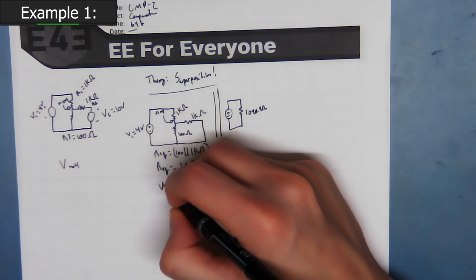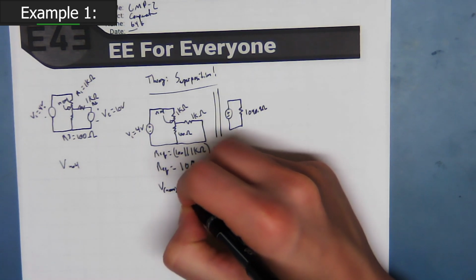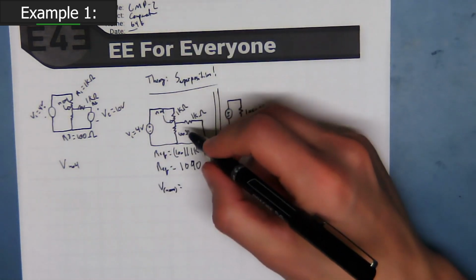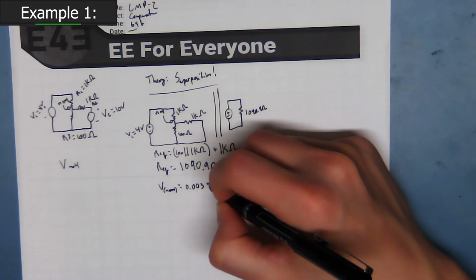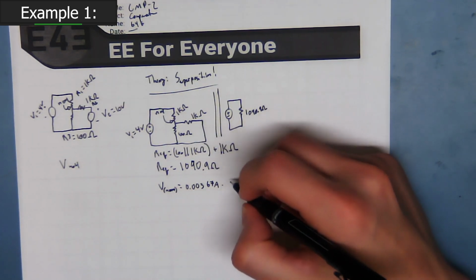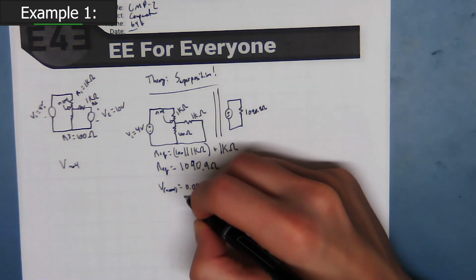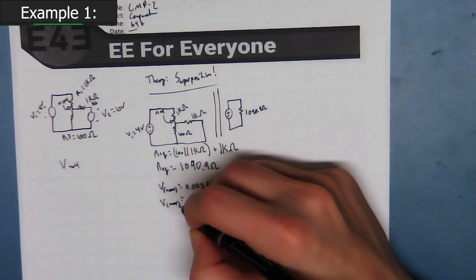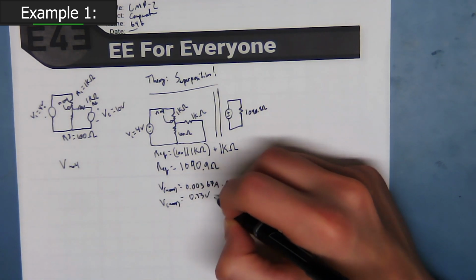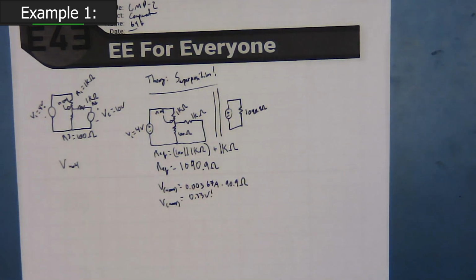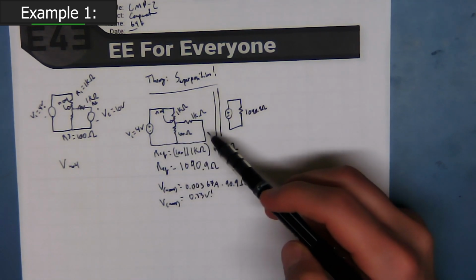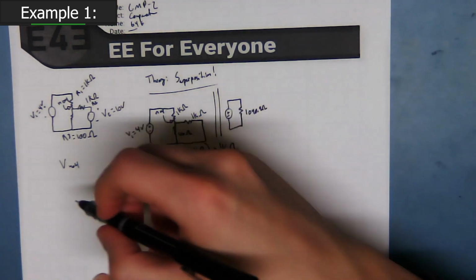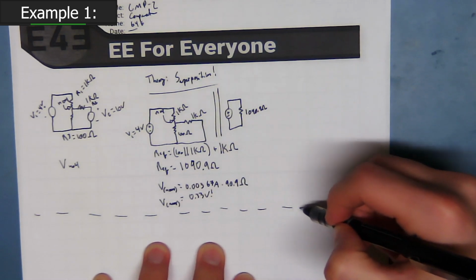So we can use voltage, in this case, at node 4, is equal to the current flowing through these two resistors in parallel, which is 3.7 odd milliamps, and multiply that by our 90.9 ohms, or 0.33 volts. Okay, but that's not our final answer. That's 1/2, right? We were only looking at this 4-volt source. What about the other one? Yeah, that's fair. That's fair. So let's consider that.